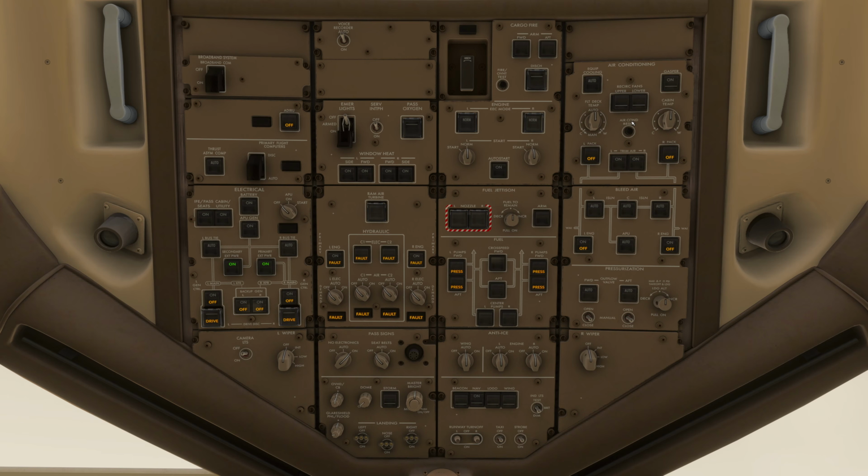Basically, this is going to stop recirculating air around the airplane, and you will always get fresh air from your external ground conditioning unit. That's why you want this off, to improve efficiency. But if they are on, you are not damaging your system. You are just not using it at its best. So keep it off.